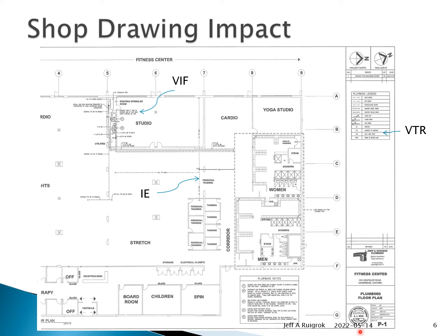Anyways, we're going to take a look at a few components of this drawing, some of which you will recognize, which is this title block. It's a vertical title block, so the drawing space goes from top to bottom. Some title blocks run across the bottom, so then the drawing space is left to right. But in this case, the title block runs vertically, so the drawing does too. We have a set of symbols here, or a legend. You know, oftentimes people use different symbols depending on their software or their style or whatever. Anyway, so if you're going to use some different symbols, you can always provide a legend, which Gabor did here. When you have things like revisions, you can leave them open-ended.